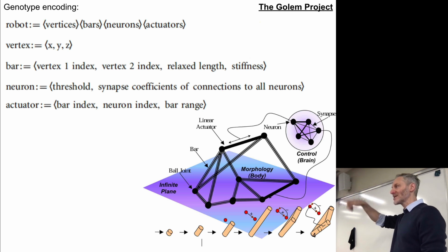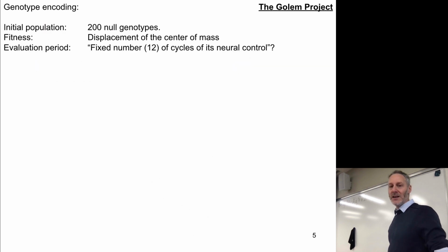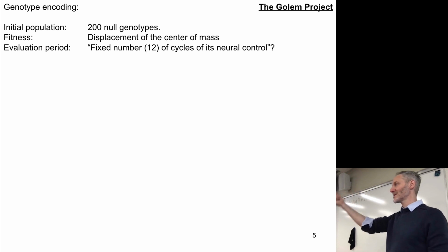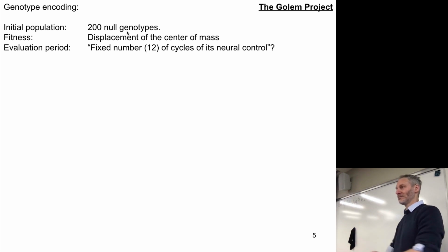And as they're running the physics engine and the time steps are elapsing, they let that CPG emit 12 cycles. When that sinusoidal pattern is done repeating 12 times, they end the simulation, they measure how far the robot has traveled in the simulator, and assign that single distance, that single floating point value to that robot and its genotype.